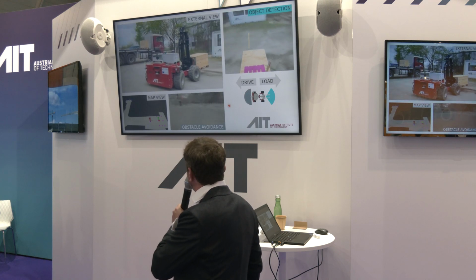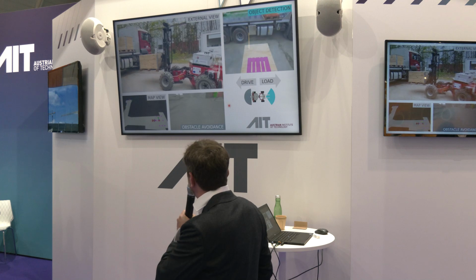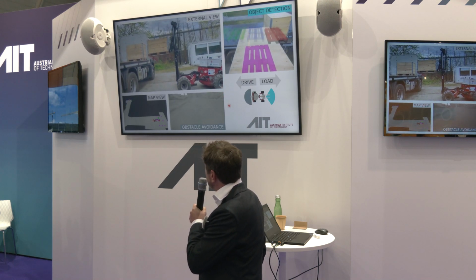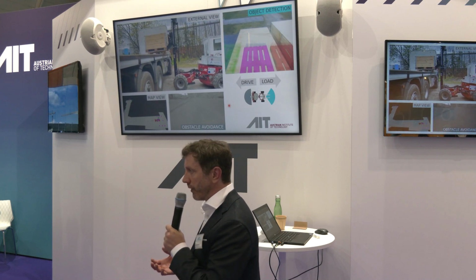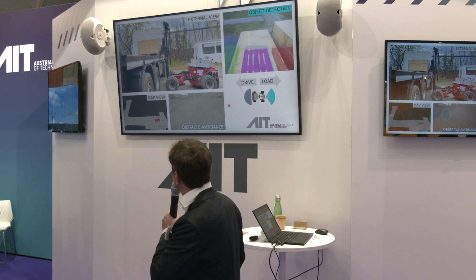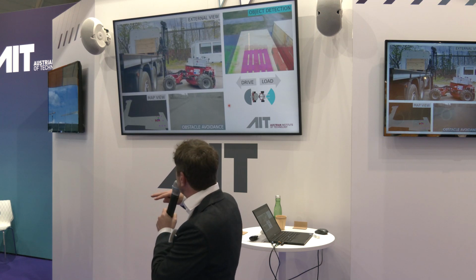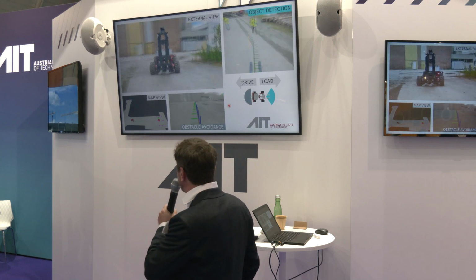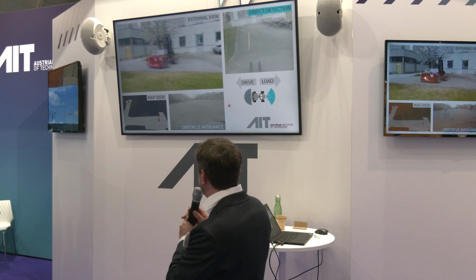I want to just emphasize one more thing here. Here we can see something which is very important for robustness, that we use the mechanical sensors also as a feedback for the system control. For example, here the forklift, its fork more or less feels where the loading platform is and then goes up and out of it. And whenever we could do things like this, they are far more robust than everything we could do with any sensor. So the tactile measurement is very accurate usually.